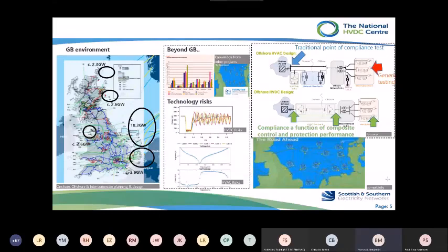From an HVDC standpoint, we are transitioning from an environment of synchronous generators with inherent behaviors to, as Christine mentioned, much more complex control-based behaviors, which are based on current loops, and current loops can go wrong. The HVDC risk slide you see relates to the tracking of a PLL through a fault ride-through event, and how the tuning of that PLL would change its performance across different levels of system strength.